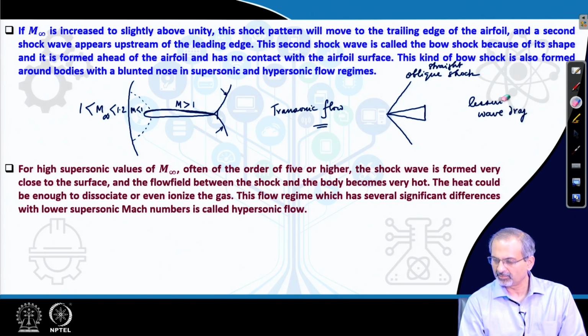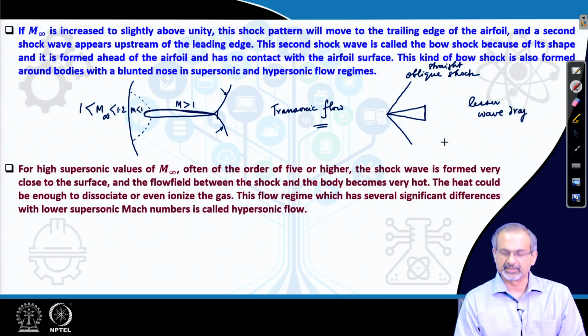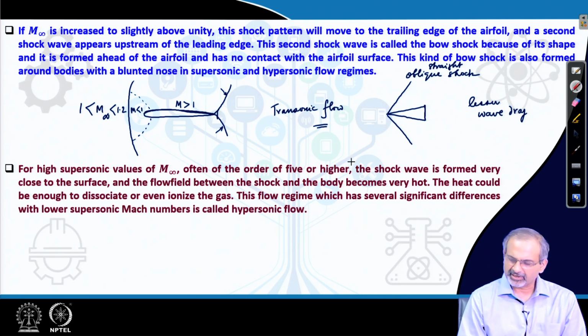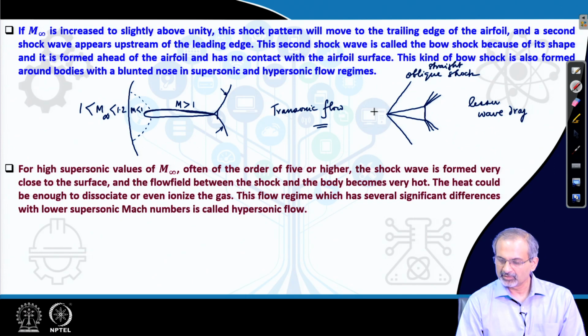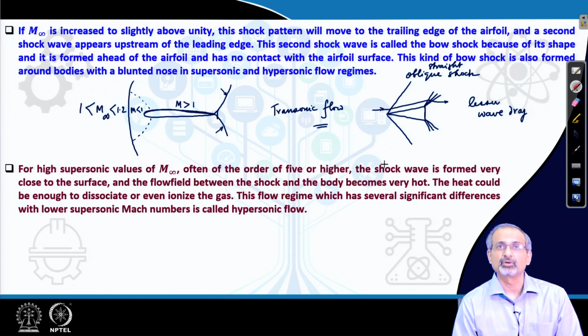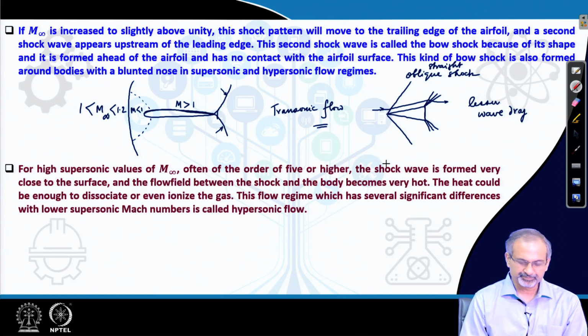So, these kinds of sharper shapes are more preferred at supersonic speeds with a lesser drag penalty, and you now know how to draw the flow field. There will be an expansion here further because the flow is turning away. So, how would the streamlines come in? They will come in like this, they will turn slightly through the expansion and become like this. I am not drawing it at the lower part, you can do it yourself later on.